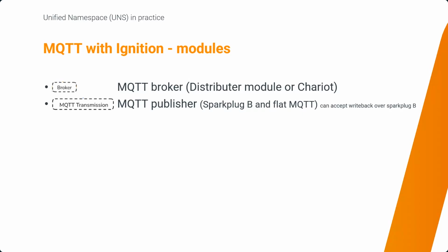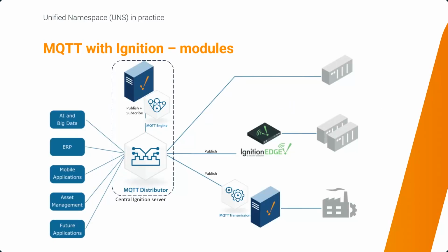So as an example, and I go back to the previous slide, an Ignition Edge system can, for instance, have a tag, a value called set point temperature for a tank. And that set point temperature, the value itself and the tag, is made in this Ignition Edge. It can publish that data to the broker and to another Ignition server. The other Ignition server is able to write back on that tag if write-back is enabled. However, the tag needs to be made by the Ignition Edge.